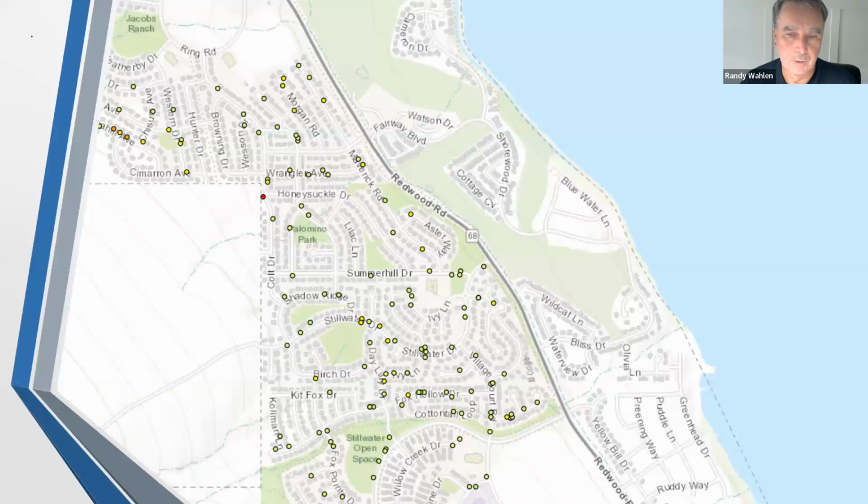This is a map down there where we mapped their faults, or the displacements, in sidewalks. Green was 1/2 inch, which is interesting. 1/2 inch is not a very big fault to have to map, but it's what people can be sued over. It's where their liability starts. So they had a lot of greens, some yellows in the 1 inch range. Orange would have been 1.5 inches, and then red 2 inches. If you get a 2 inch fault, that's a pretty big sidewalk problem. So we do a lot of that. They look at obstructions, different things.